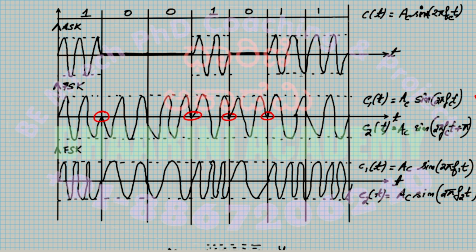So whenever you send one of the symbols, send the 0 phase. Whenever you send the other symbol, you add a phase of 180 degrees to that and send. That is the phase shift keying. So you see, whenever one is there, normally you draw a sine. But as soon as there is a change in the phase required for a symbol being changed to 0, reverse it. You can see the red marks over here. There the phase is said to be changing, right? The signal is going up, and all of a sudden the signal comes down, which means a change of phase. Okay, that is what a change of phase is. So whenever 0 changes to 1, 1 changes to 0, 0 changes to 1, and so on, this happens.